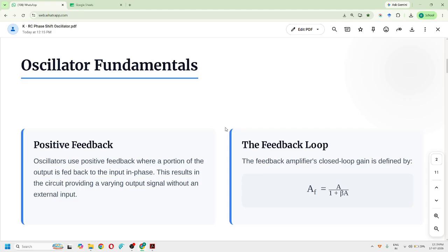Okay. So an oscillator generally is going to generate some waveform continuously with the input DC biasing. With the DC power, it is going to give you a continuous waveform. It can generate different frequency components and different kinds of waveforms, either sinusoidal or non-sinusoidal signals, maybe a square, triangular or sawtooth. It also creates a periodic waveform. After some time period, you are going to have the same amplitude. So that is the objective of the signal.